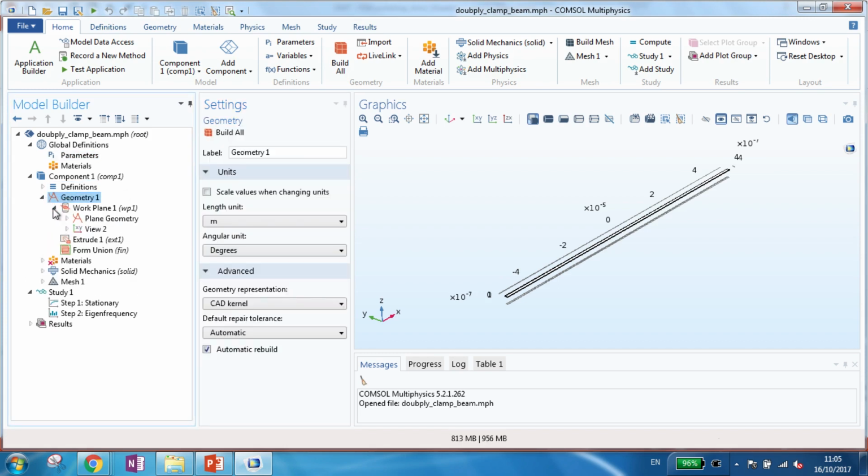As I said, if you go with this pre-stress analysis eigenmode, it would just automatically put in 2 steps. You can start with pre-stress and add the other one, and if you want to do more complicated stuff, you can. That's the logic. This is how we do multiple steps. We just stack them, and there are settings where you can feed the values of the first as initial values for the second one.